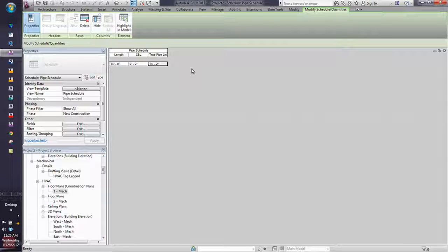Now, one of the other things that we did too is in all of our fluorescent light fixtures, we include two connectors. We have a normal power and an emergency power, and we have both emergency and normal lighting in one file. Now, you got to be kind of careful about that because you are adding extra connectors. You can't turn the connector off, not yet. They're working on that part, and we might get that in the next release where you can turn a connector functionality off. That's one of the things that we've been hearing about already. So that would be something that would be really cool. You can say, don't take this connector into account. Then you can put all of them in there you want. Pretty cool? Yes, sir.